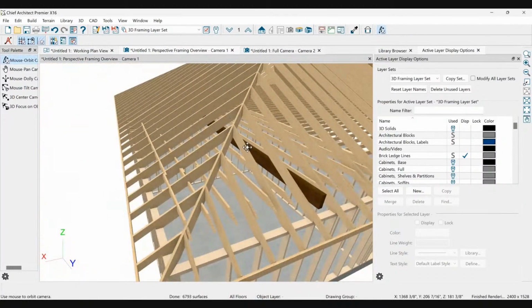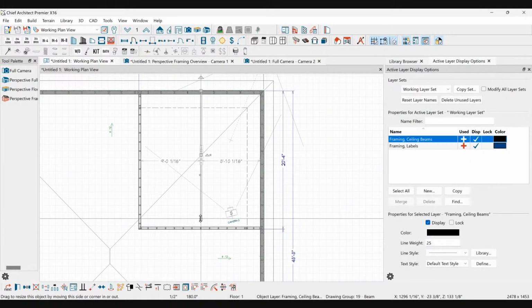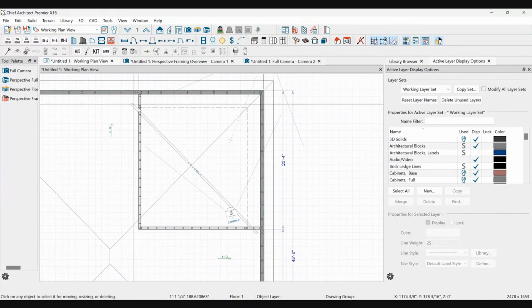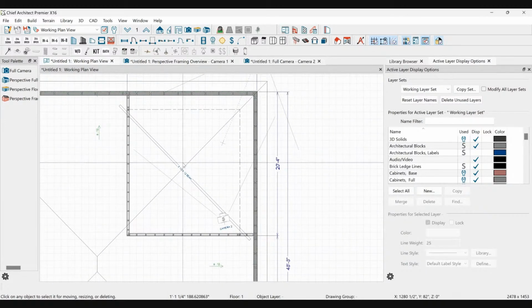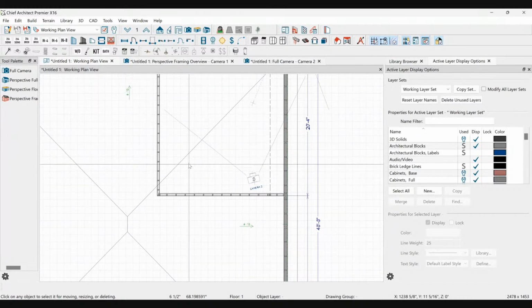And if I can't run a beam across, then the only thing that I could possibly do is turn the beam at an angle and try to cross the room like this, which would just be stupid and weird. I could do that and now I can brace the hip over here, but most people are going to be like, I don't really want to make a 45-degree beam. That's kind of weird. And so they're just not going to put a beam in. And they're going to rely on whatever brace they can get.